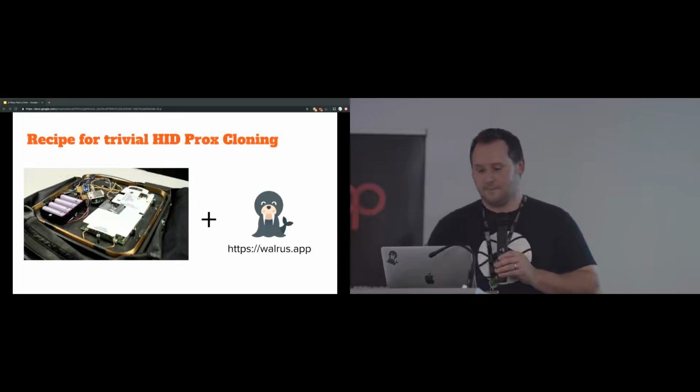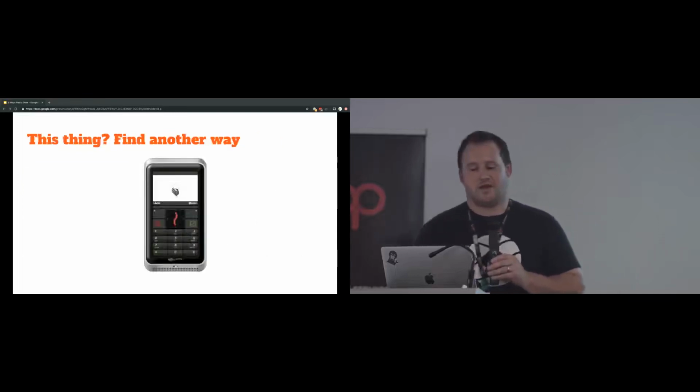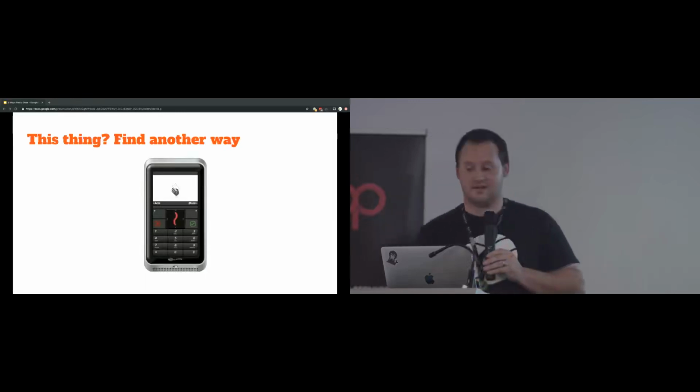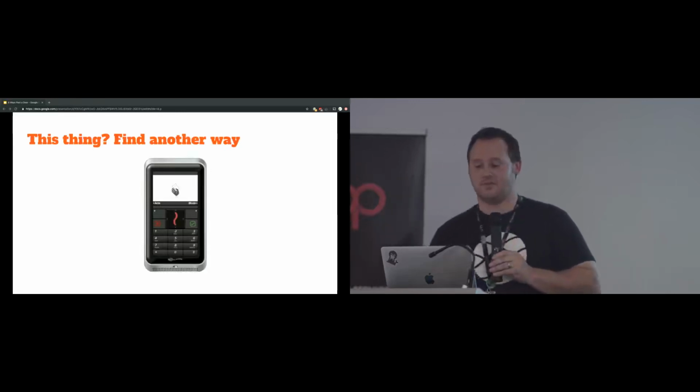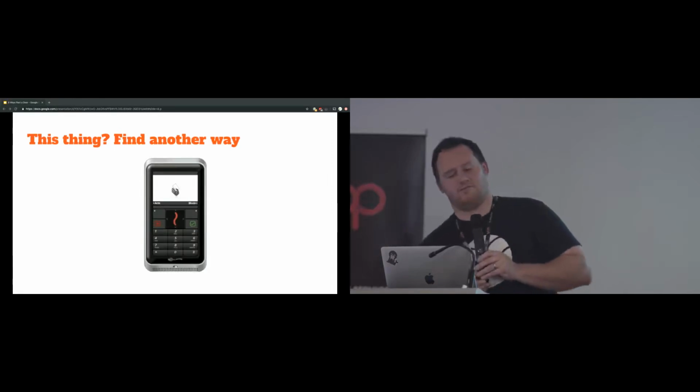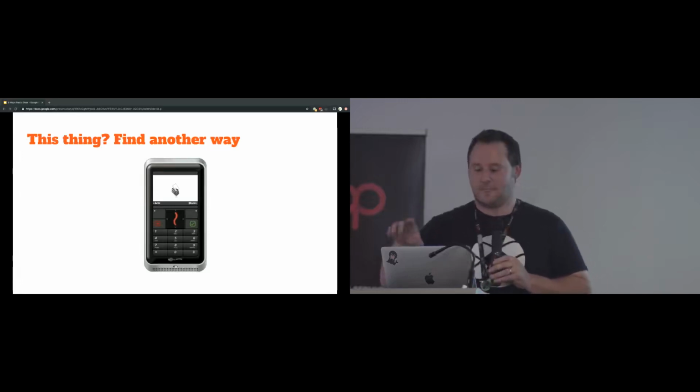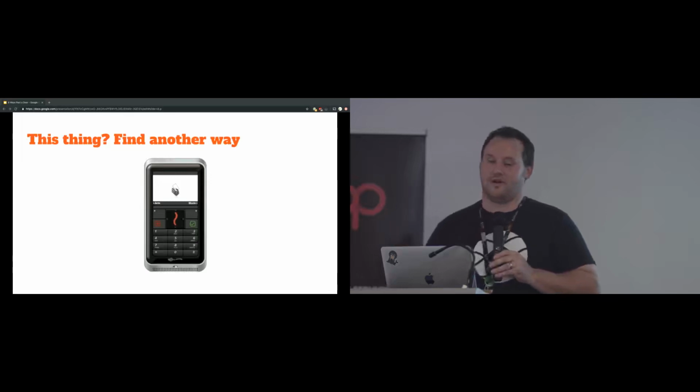It's trivial. But on the other hand, we're starting to see a lot more sites that are using systems like this. This particular beastie is a Gallagher T20. Unless the integrator has crippled it by either ticking all of the legacy compatibility options, or they've made some implementation mistakes that I'll hint about but not talk about today, these generally are using a cryptographic challenge and response between the card and the reader. You're not going to compromise that anytime soon. If you see a modern card system and it's not operating on 125 kilohertz, meaning it has legacy support enabled, just move on to another attack.